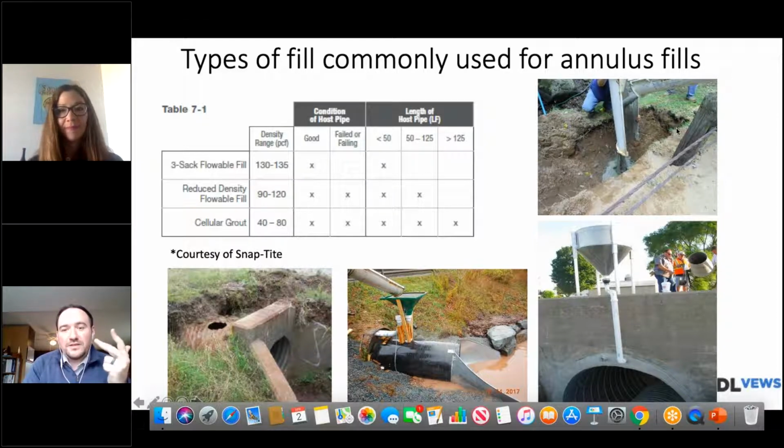There's the pump pressure, there's the pressure at the hose. But the key is really the grout pressure at the pump may vary depending on the equipment. What is crucial is that you always talk to your lining manufacturer, whether it be Snap-Tite or someone else, what should we limit those pressures to, and then ask them more deeply where do those pressures come from and how can I mitigate those risks.